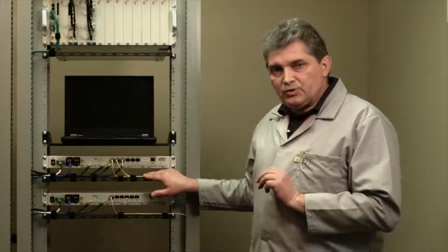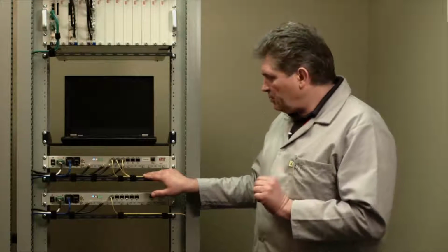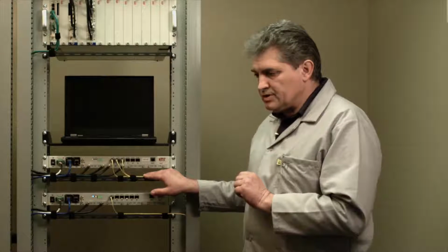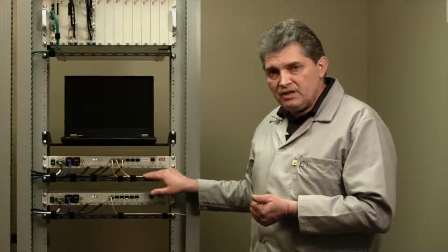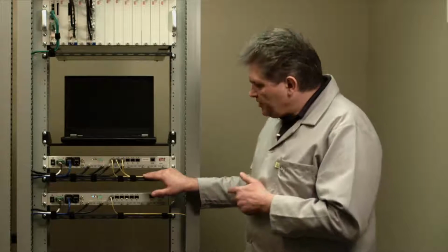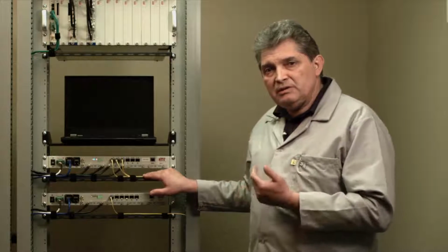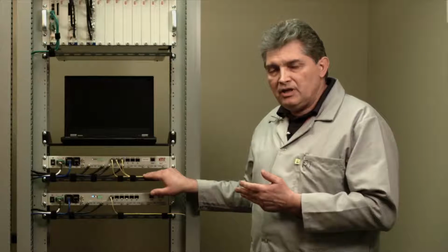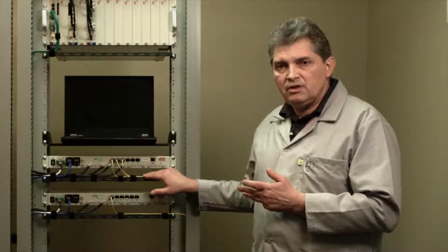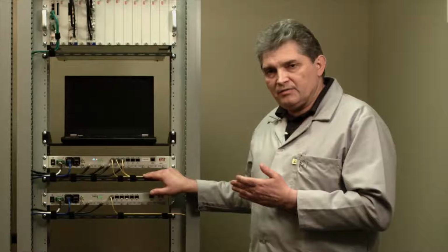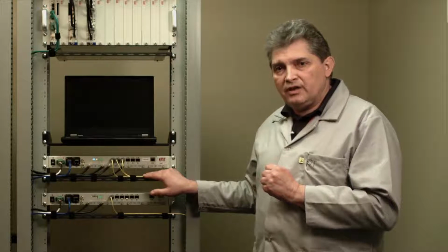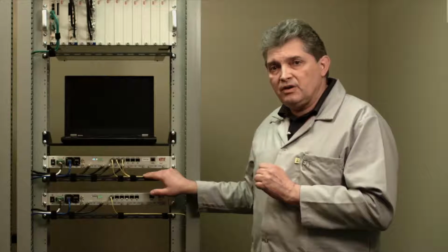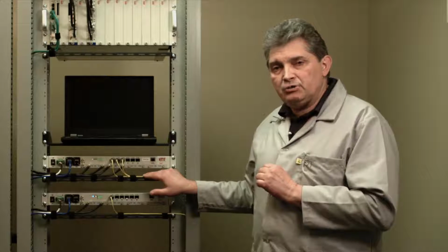The system supports multiple bands. For the North American market, the system supports the 700 MHz band, which includes lower ABC and upper C, the 850 MHz band, the PCS band, including subband G, and the AWS band. We also support Sprint 800 and the 2300 band that is currently dedicated to AT&T.